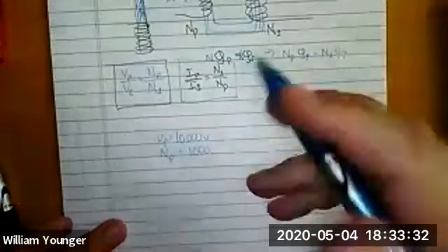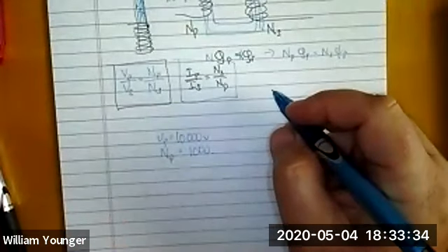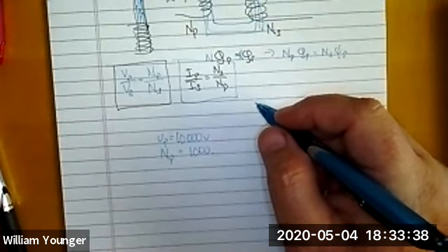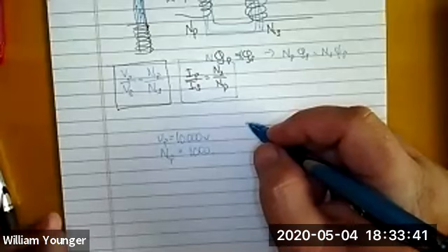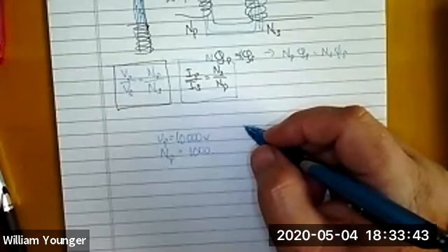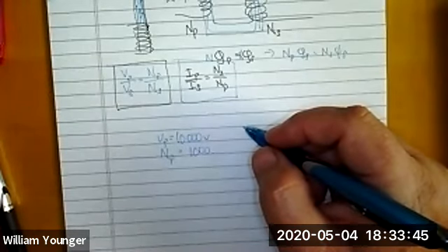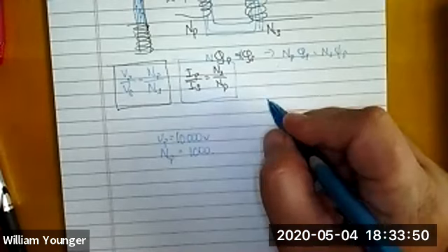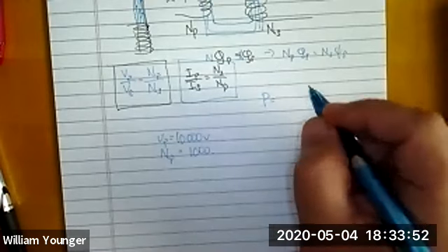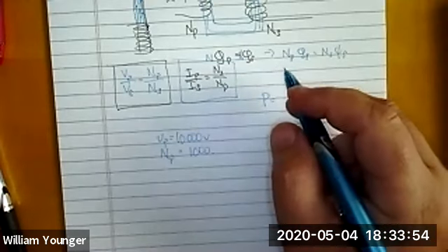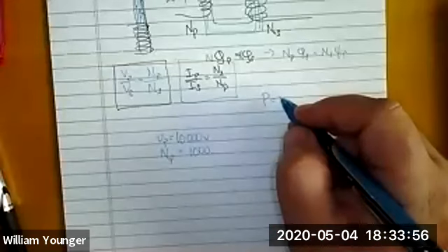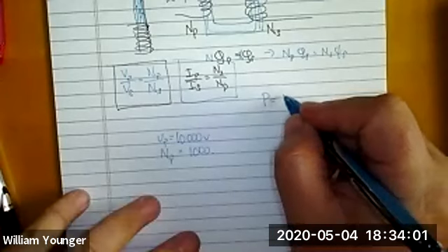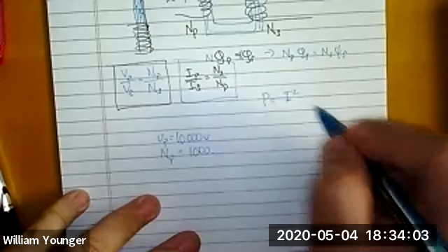Well, it turns out that you can't really change the resistance of the wires. You're basically going to choose a metal, and then the distance from the power plant to the substation is fixed. So whatever that metal is and however large a gauge you use, that's going to dictate what your resistance is. So it's not much use to talk about the power as IV. It's more important, because you don't know how much the voltage is going to drop across that, to do basically I squared.